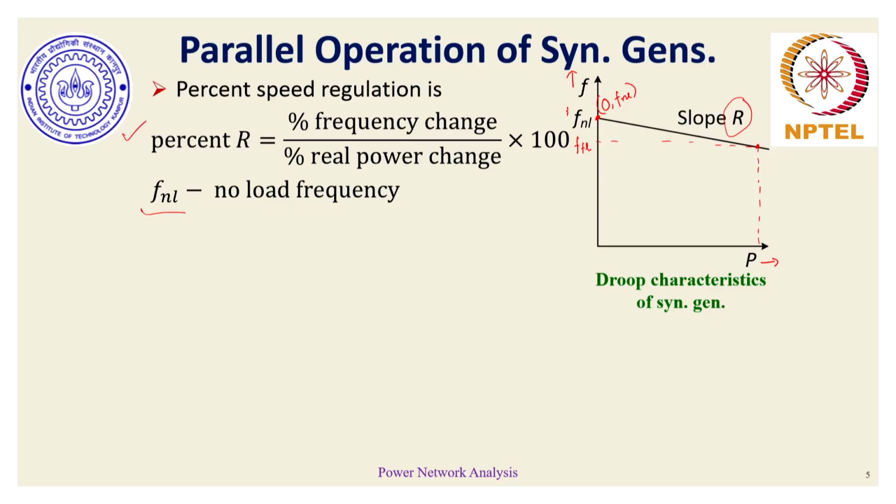So for rotating devices, the kinetic energy is proportional to the square of speed of that particular rotating device. So if the speed tends to go down, the rotor kinetic energy tends to go down from no load condition, and this release in the kinetic energy of the rotor is essentially given as an additional output to the synchronous generator to feed more electrical load.